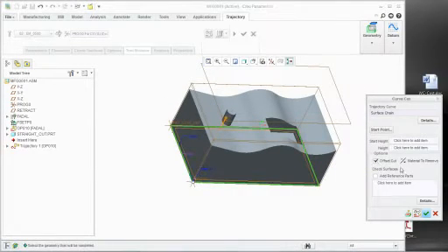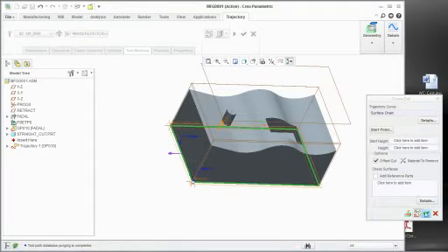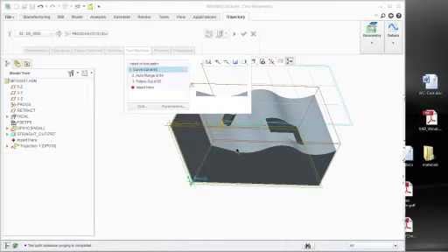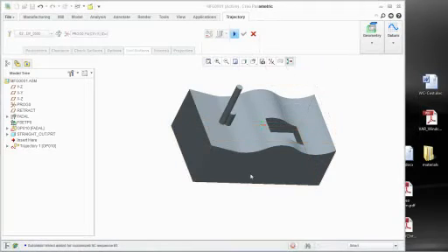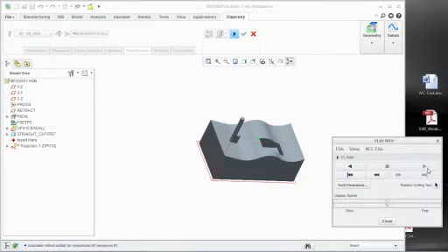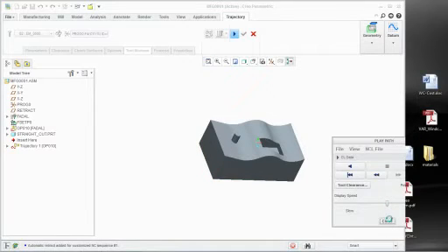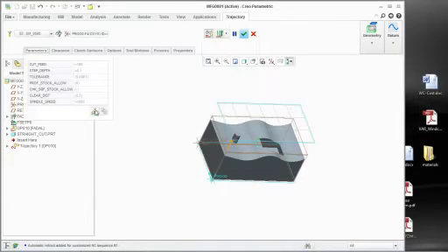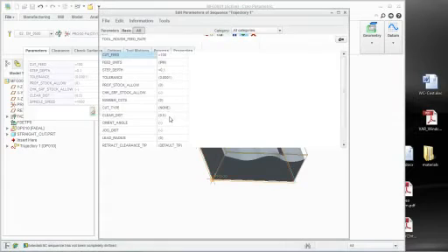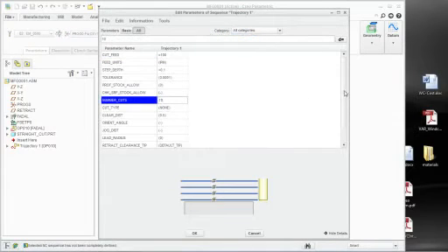We want to offset the cut. We want to offset it to the outside. Okay, now, what I did here was just created a quick little toolpath that runs around the edge. Okay, pretty simple function. Now, quickly, I'm going to come in and change the parameters of this guy, and I'm going to step it down a few times. Let's just say we're going to step it down 10, and then we're going to put in step depth.